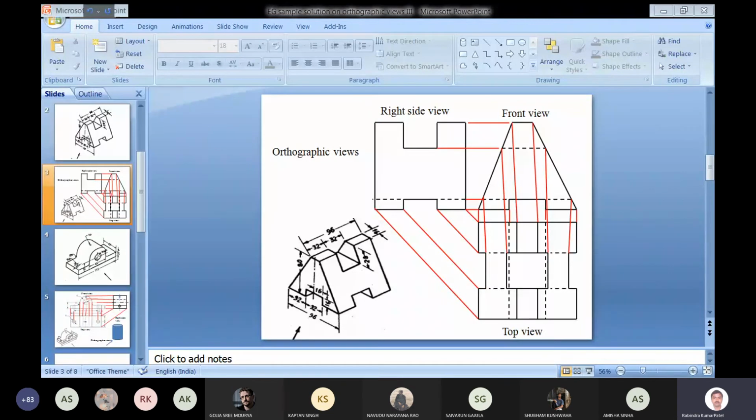So this C type shape will be there in the top view, and it should be aligned with the front view. If we consider it the other way, it is quite possible that you get the same dimensions on all sides, like 45, 45, 45, so that may create confusion. Otherwise, if dimensions are different, you won't get aligned views, and you can directly correct the mistake. So here, the first one, A, is the top view.